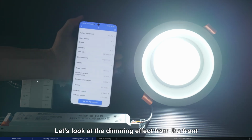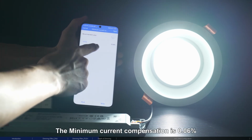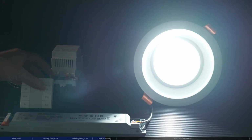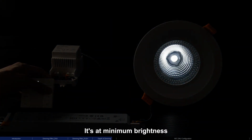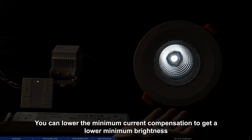Let's look at the dimming effect from the front. The minimum current compensation is 0.06%. You can set it lower to get a lower minimum brightness. Off. On. Long press to reduce brightness. Smooth and deep dimming, flicker-free. It's at minimum brightness. You can lower the minimum current compensation to get a lower minimum brightness.